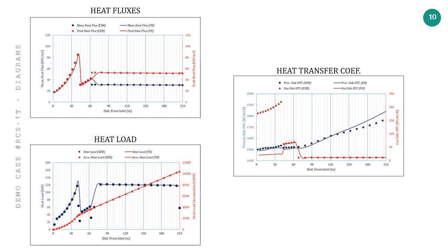Now, let's talk about the heat transfer coefficients, HTC. For the process side, the blue lines, the match is excellent. But you might notice a deviation in the gas side HTC, the red lines, at the beginning of the convection section. Let me clarify this, because it's an important technical detail. In FHinfinity, we calculate the fin tube HTC based on the total surface area. However, Aspen EDR reports it based on the bare tube area. This is simply a difference in definition. If we convert the bases to be consistent, the red lines would overlap perfectly. So rest assured, the underlying calculation logic is fully aligned.